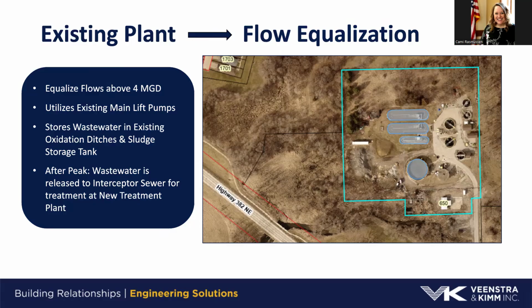So this is handling a couple of things. One is giving you essentially more capacity with your existing plant because you don't have to handle those peak flows all the way through the plant. We can shave that off. So you get a little bit more growth capability. And then we also have the ability to protect the plant in emergency situations.